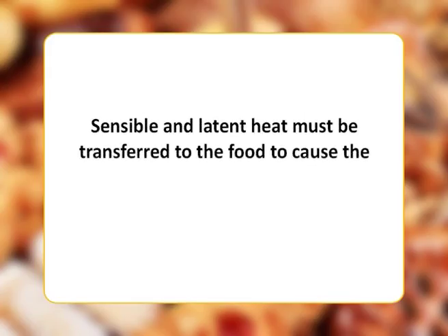Dehydration is usually described as a simultaneous heat and mass transfer operation. Sensible and latent heat must be transferred to the food in order to cause the water to evaporate. Placing the food in a current of heated air is the most widely used method of supplying heat. The heat is transferred by convection from the air to the surface of the food and by conduction within the food. Alternatively, the food may be placed in contact with a heated surface.